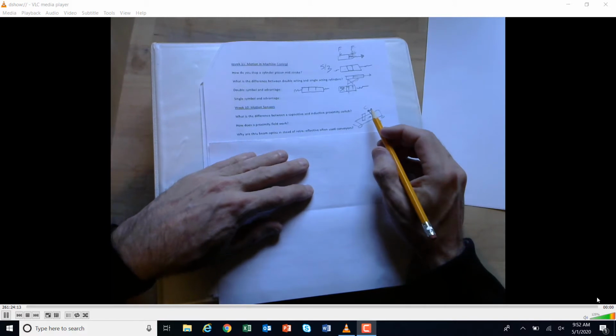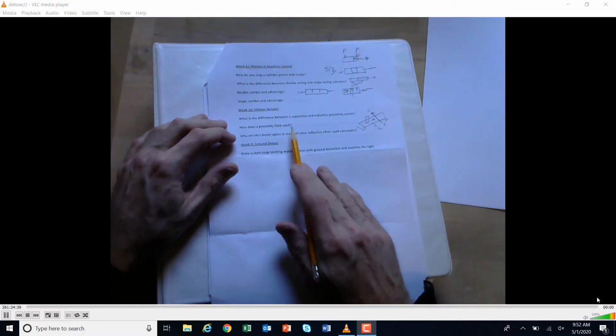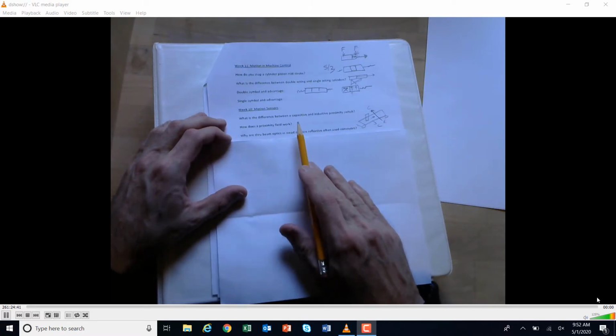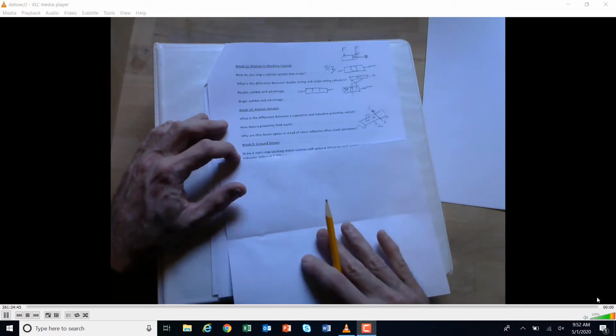Okay, whereas if you get a retroreflective, you could get some variation on this right here, and it might not bounce it back to the collector here. Okay, this is just simpler. It's easy, and it's almost bulletproof to sense things coming down a conveyor. Okay, and we went over all the different motion sensors about how they worked, and you'll want to review the lab solution that I gave you.